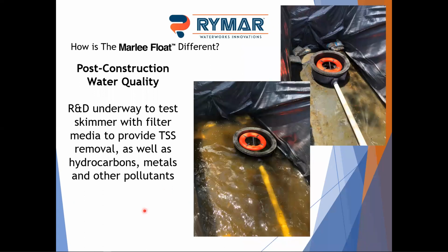One thing we're really excited about, and just a little bit of a teaser here, we have R&D underway to test a skimmer with filter media for post-construction water quality. So we're really excited about this. We're pushing hard to get it completed, but it'll be an add-on around the skimmer, and we'll have a specialized filter media that will be designed to not only remove TSS, we expect to hit easily above 85% TSS removal, but the media will also remove hydrocarbons, metals, and we're working hard to even include phosphorus and some other pollutants. So that's kind of the next phase of where we're headed, and super excited about it. We're working hard to get that completed, and we'll keep you informed as we do.